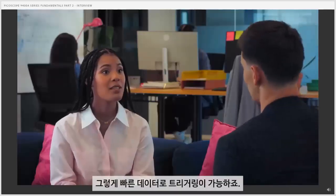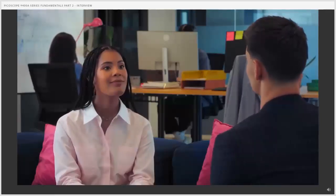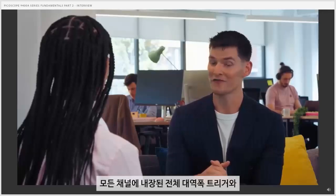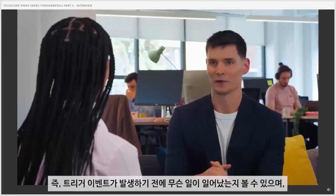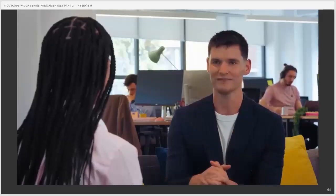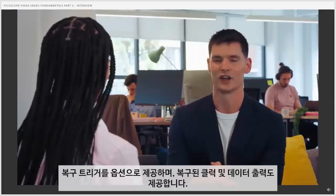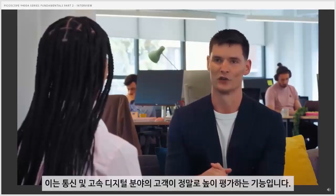And triggering. With such fast data, getting a stable trigger is often a nightmare, even for us. We made sure the 9400A series has a super robust triggering system. It offers a built-in full bandwidth trigger on every channel, with pre-trigger random sampling capabilities. This means you can see what happened before the trigger event, which is incredibly useful for root cause analysis of intermittent issues. Plus, for your datacomms work, we offer optional clock recovery triggers up to 11.3 gigabits per second, and even recovered clock and data outputs. That's a feature our customers in telecoms and high-speed digital really appreciate.